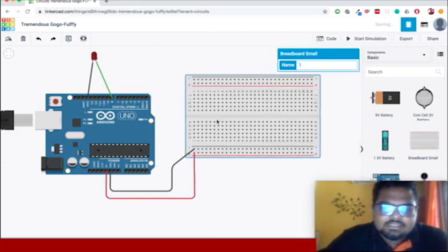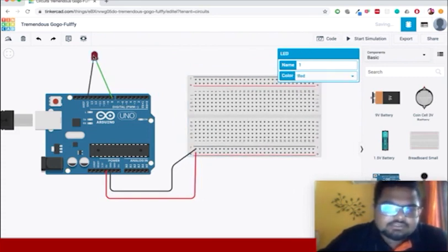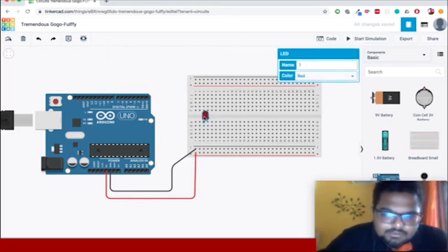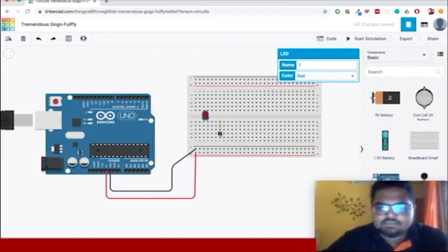And now what I'm going to do is, instead of connecting the LED to the Arduino board directly, I'm going to fix the LEDs through the breadboard like this. So you know that in a breadboard these lines are connected and these railings are connected vertically, or in this case it's horizontally and this is vertically. So you can see they're connected like that. So this line is all the same.